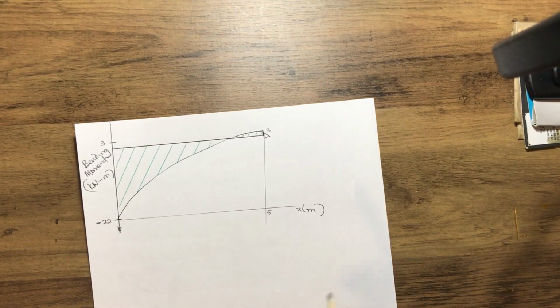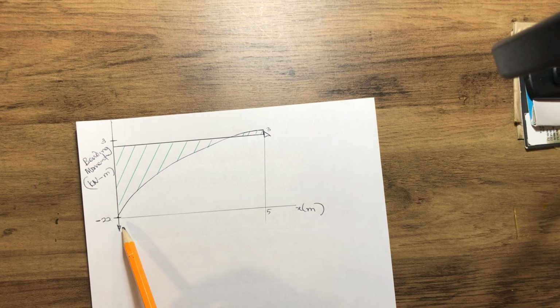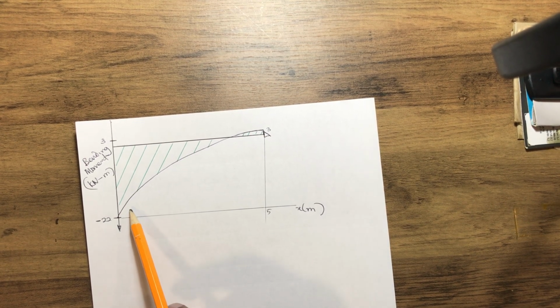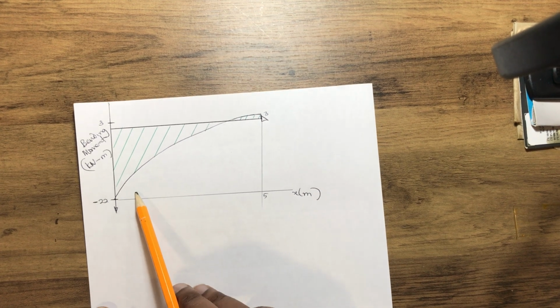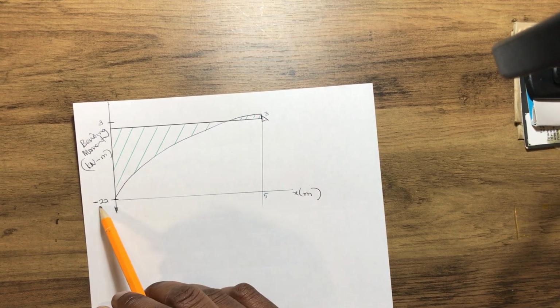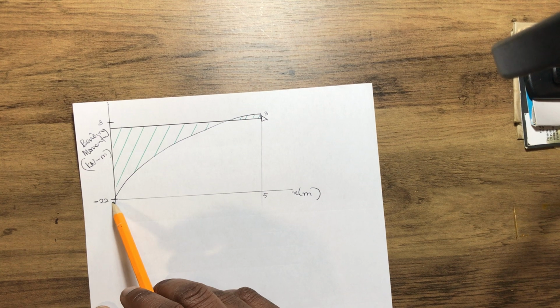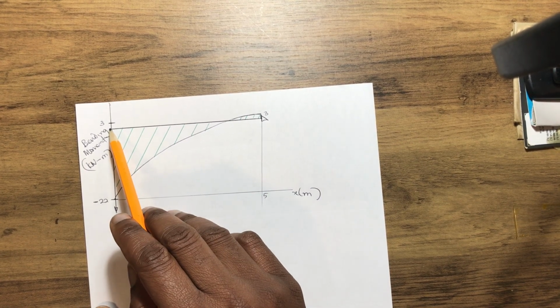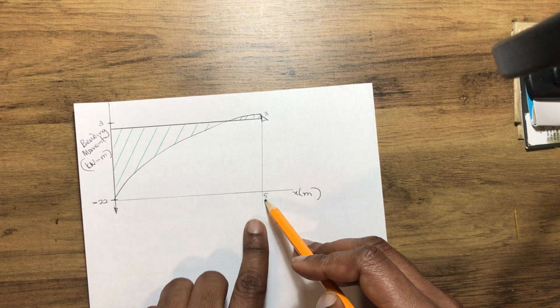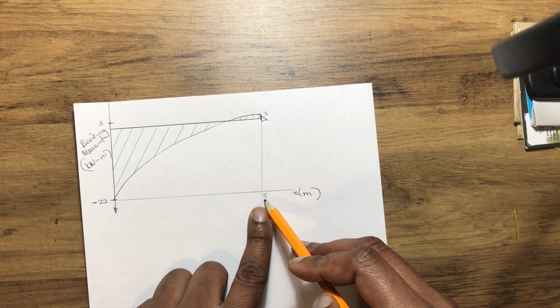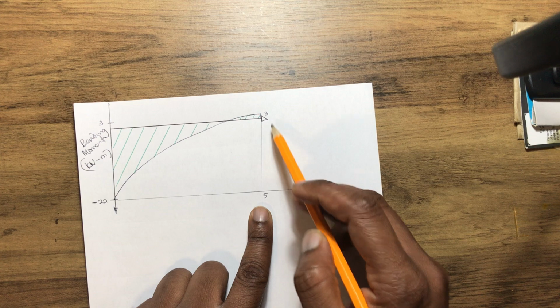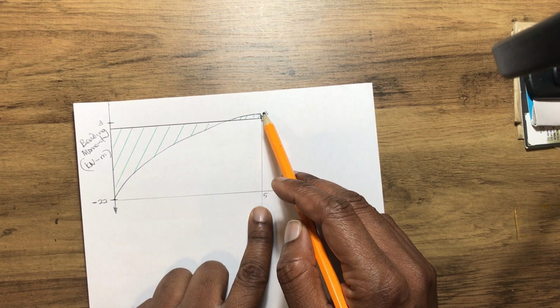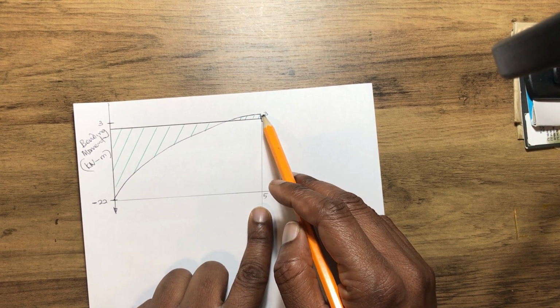Also, our bending moment diagram from the equation we got for the bending moment gives us this diagram. At minus 22 kN meter bending moment, we have 0 distance, and at 5 meters distance on the beam, we have a positive 3 kN meter bending moment.